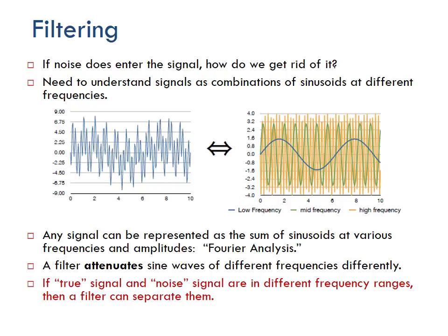How does it sound? And as a tip, you're going to hear totally different things if you tune your circuit right. If you put a low pass filter on, it's just going to be the bass of whatever you're playing. So whenever you have a subwoofer, the subwoofer is just letting your low frequencies through, because you don't want to put your high frequencies on the sub. It doesn't come out sounding very well. Likewise, you don't want low frequencies on your tweeters. That sounds miserable too. And that's why if you listen to music out of normal computer speakers without a subwoofer, usually you don't get any bass in there. It sounds kind of tinny, kind of crappy.